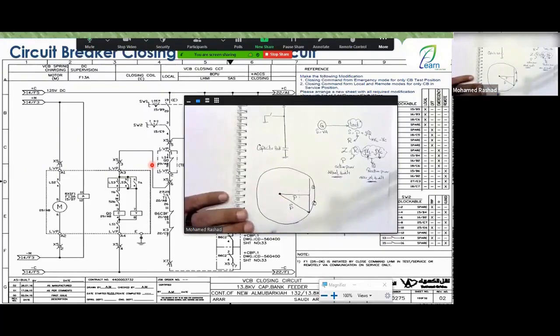Now, what matters to me is that the more Q decreases, like reaching up to here, I can reach more P. So here's P, and if I reduce Q to here, I can reach this point because it's the same S. The S has moved along this semicircle. So if you reduce Q by this amount, you've increased P by this amount. This is what concerns me.